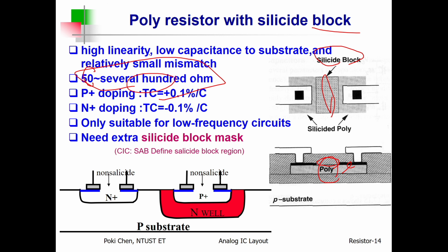It means the resistance is enlarged by 2 orders, simply with the silicide block. And look, it looks quite easy, right? But it is really expensive, because I told you, you need one extra mask called silicide block. That's it. If you like it, pay for it. It's your own business, instead of mine, it's up to you.